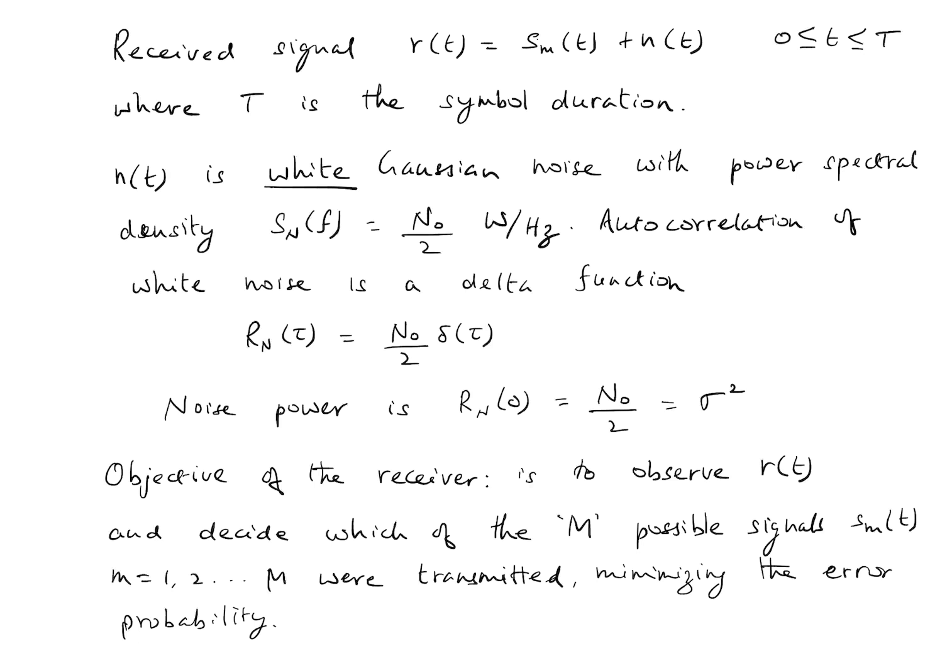Now, when we look at the received signal r(t), we want to analyze it over a duration T, which denotes the symbol duration. So we represent each symbol over a certain duration of time, which we call capital T, and we are interested in observing the received signal r(t) for that duration and making some decision about what was transmitted. So all our analysis would be restricted to that particular symbol duration, which goes from 0 to T.